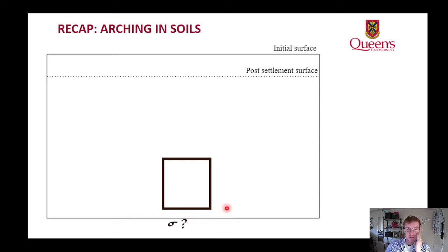So at first glance, you would probably say, well, we have some uniform settlement, we're going to have some soil of mass gamma per meter cubed, and we'll have some known height to work with, etc., etc. You might work out that overburden pressure. If you're really the type to think ahead, you might go as far to say, let's grab the concrete handbook and discern what the mass of the culvert itself acting upon itself would be, and then you might think that you're onto something. And for a common sense approach, that's actually pretty good.